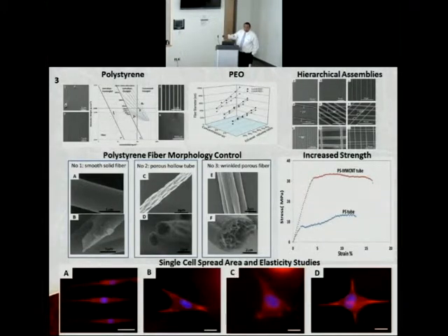and you can start making tubes. And then you can also have fibers with multi-channels inside them. So you can control this repeatedly. So I've been able to achieve that. Then the next thing we did was we took the same tubes, we put carbon nanotubes inside them, and we did stress-strain curves. And as shown in this curve, the carbon nanotubes with the PS are a lot stronger.